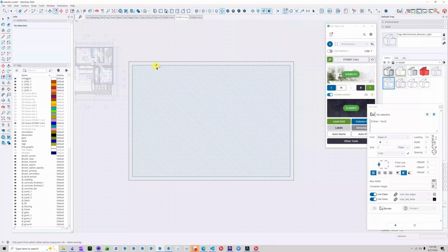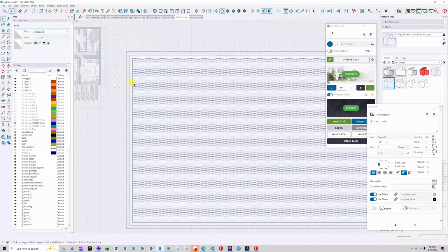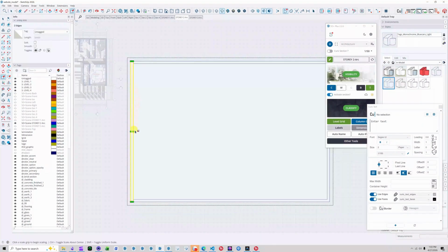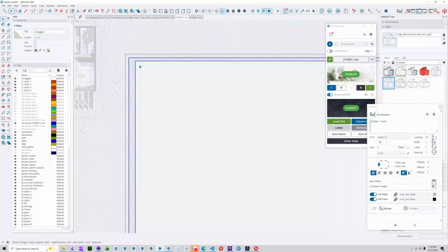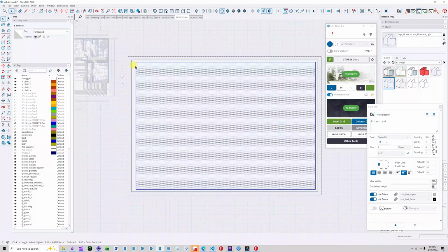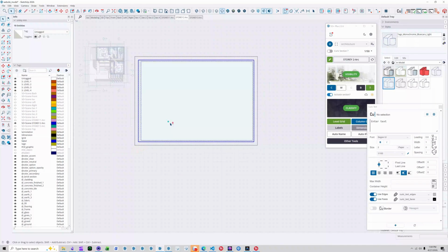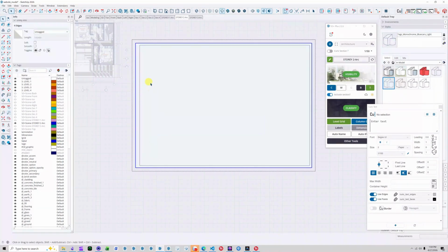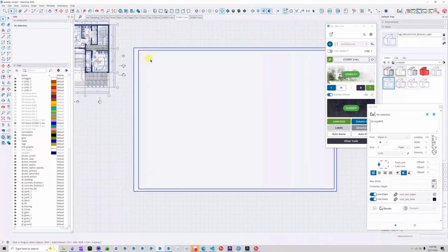Next, I'll create the safety margin line. Pay attention here. I'll enter 500 millimeters, 500, and you can see that I haven't set the margin yet. 1000 millimeters. Then I'll hide the outer part to tidy things up a bit. Then remove the frame, still using the hide command, and you'll get a shape like this.